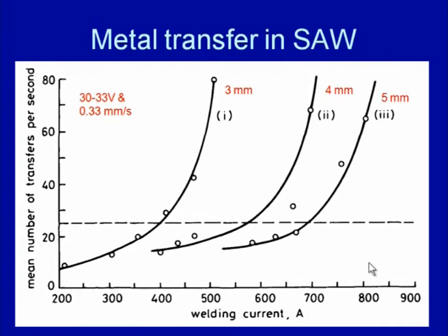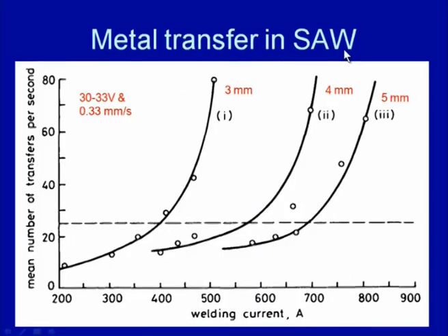We know that metal transfer is an important phenomenon in consumable arc welding processes, where the electrode tip melts and the molten metal is transferred to the weld pool during welding, and it can happen in a number of ways like short-circuiting transfer, globular transfer, spray transfer, rotational transfer, explosion, etc. In case of the submerged arc welding process, normally a discrete kind of transfer is observed, where drop by drop molten metal transfer occurs. Sometimes the molten metal from the electrode tip is transferred along the wall of the molten flux also.